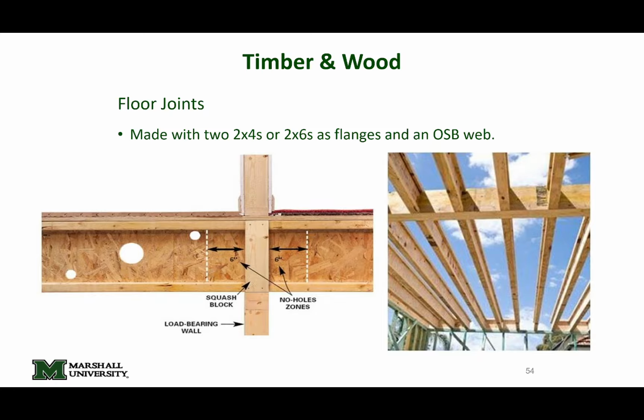And if we have, for example, a TJI joist, we can look up the manufacturer spec. Here's the moment capacity. Here's the shear capacity. Here's the EI for deflection. And so we have a problem, just pick one that works. So it's actually pretty nice in that regard.